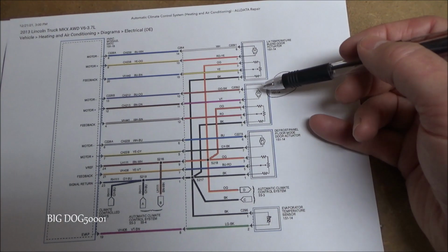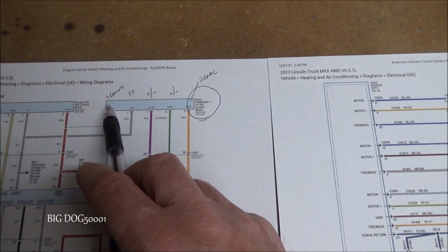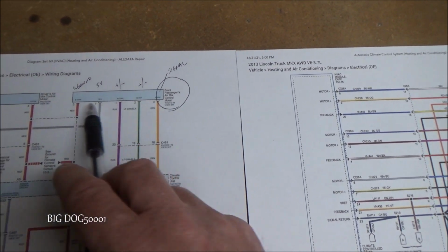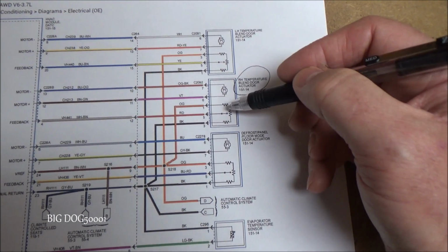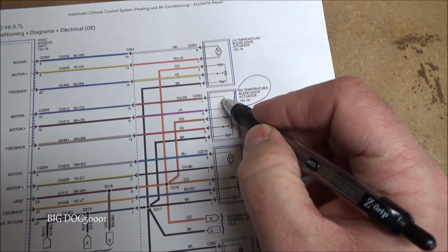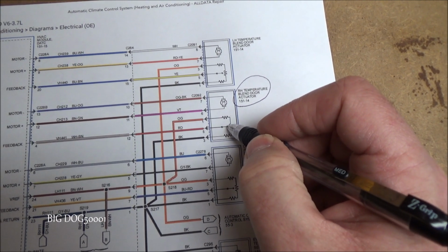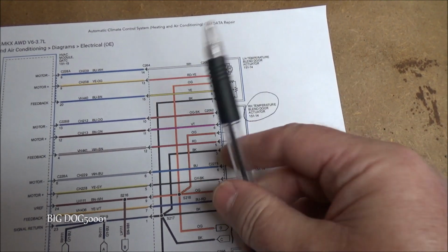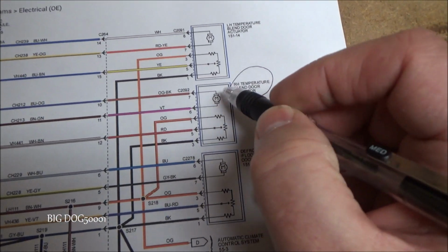But most of these are going to be 5-wire systems, just like this. The Honda's no different, 5 wires. They're just going to label them differently. Over here is kind of clear of what everything is. We have our motor here, and then we have our sensor that senses the position of the actual motor or linkage where it's at. So these 2 wires are going to power the motor itself.